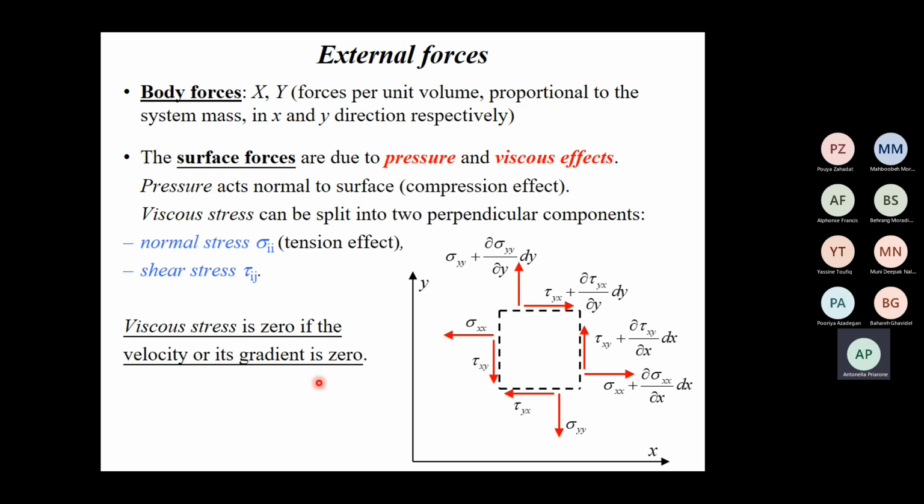But in the boundary layer you have acceleration. In the zone far out of the boundary layer, it's correct. If I have a laminar flow, I have like a still motion of a portion of fluid. But in the boundary layer that we are analyzing, you have always a gradient of a velocity.